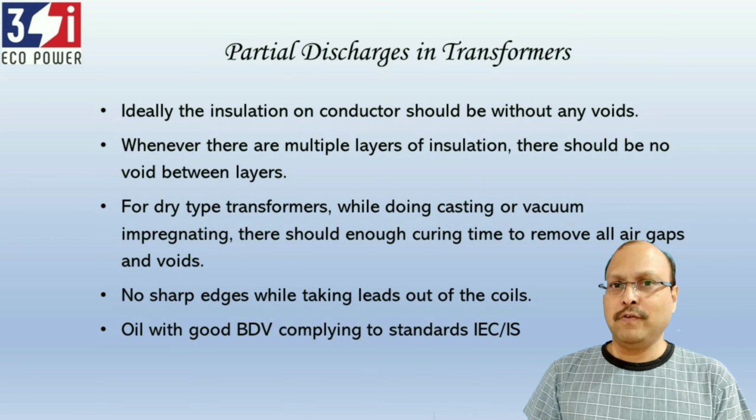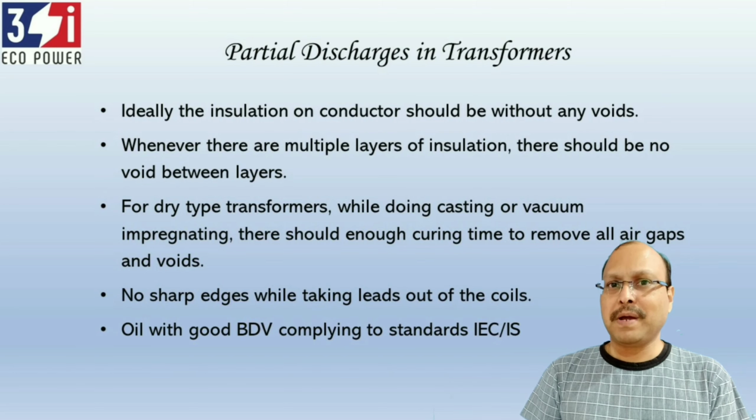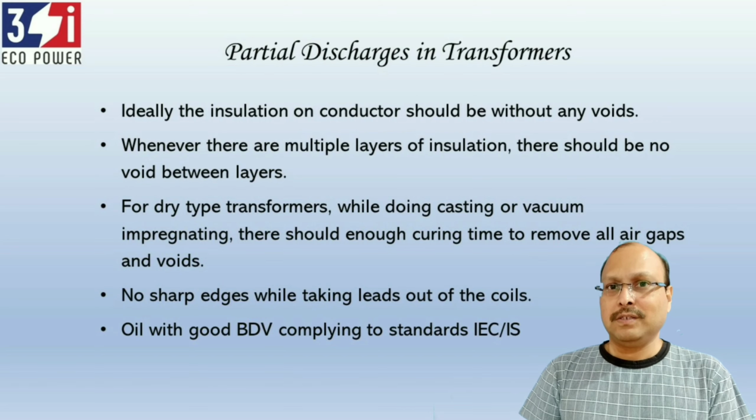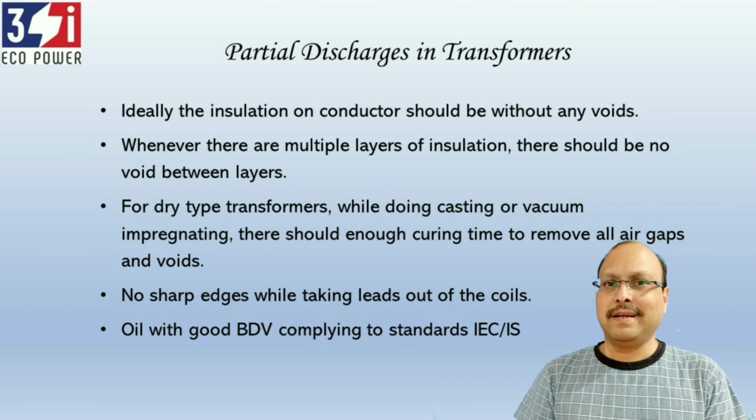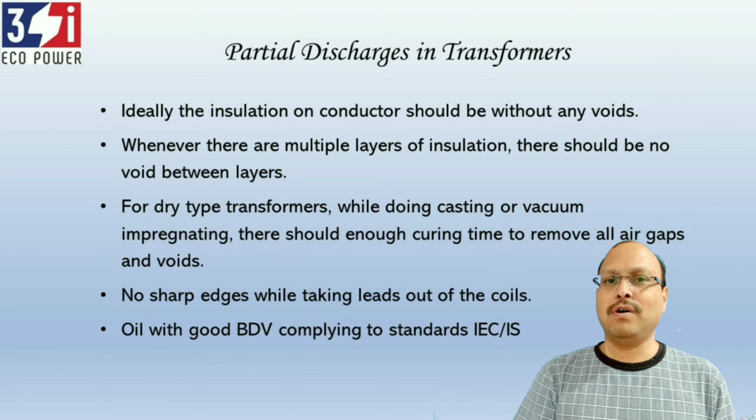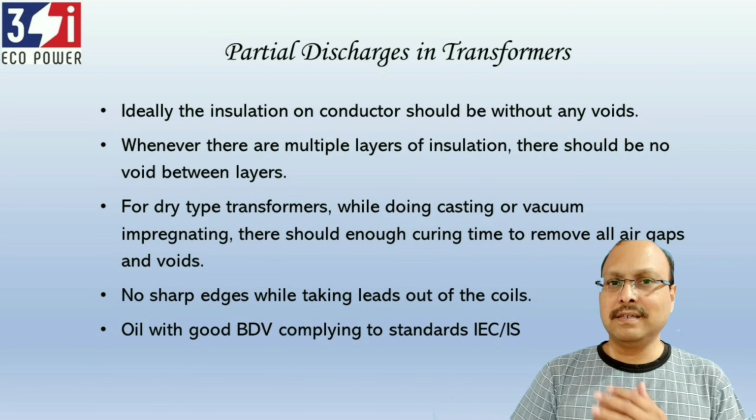And there should be no voids. Whenever there is a void, the void becomes a dielectric space, and either side of it the conductors become like a parallel plate capacitor. So the insulation becomes capacitor-like, and there will be local ionizations because of these voids. Also, if it is an oil-filled transformer, ensure the oil has good dielectric strength.